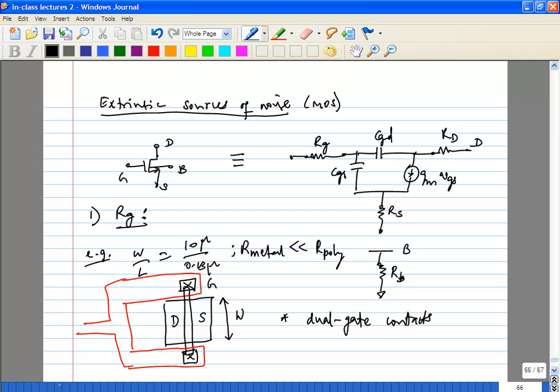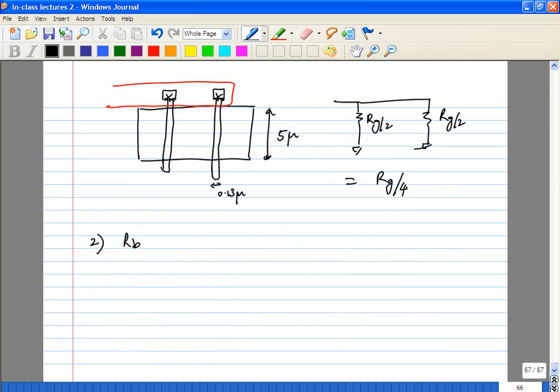That will be from the bottom side, at a 500 micron depth. So you'll have to make sure this transistor has a good bulk contact. If you look at normal RF layouts, you'll see something like this.